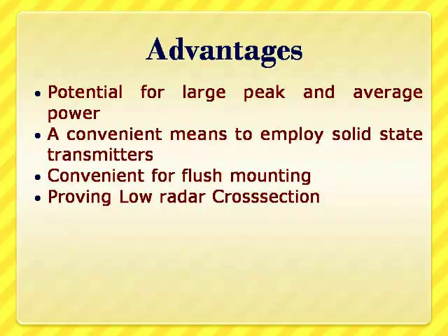There are active phased arrays these days wherein a small sized solid state transmitter is attached to the antenna element itself. By this, the feeding network complexity is eliminated to a great extent. The feeding network is now only to provide the DC input for these solid state transmitters. And the antenna array can be made by several types of antennas. They can be parabolic dishes, horn antennas, dipoles, or the new variety of microstrip antennas.